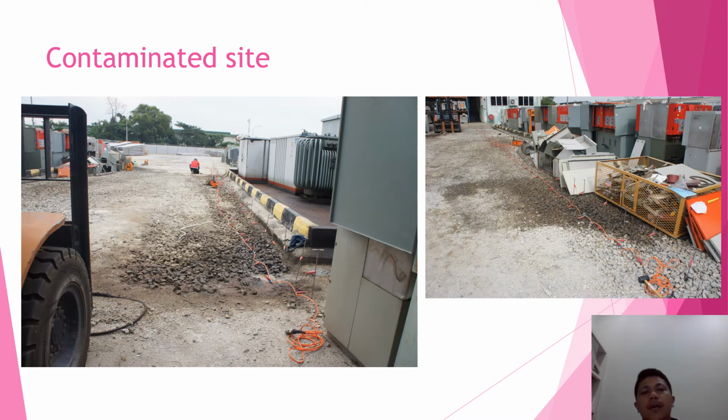Next we have somewhere in Penang, and then this one also maybe from Teluk Intan. So basically we have sites that have a transformer leak from soil with the oil. So we use the resistivity method with close spacing to see the thickness of the contaminated layer.